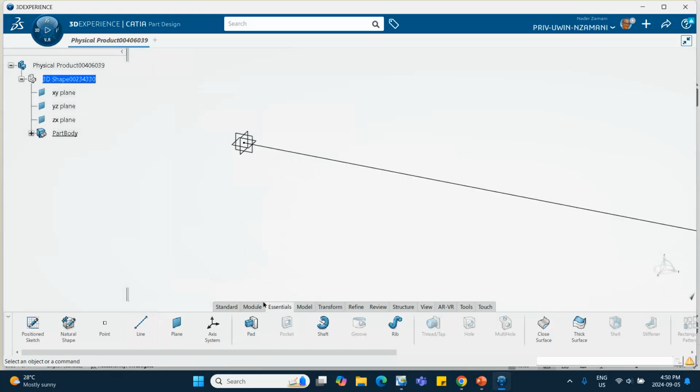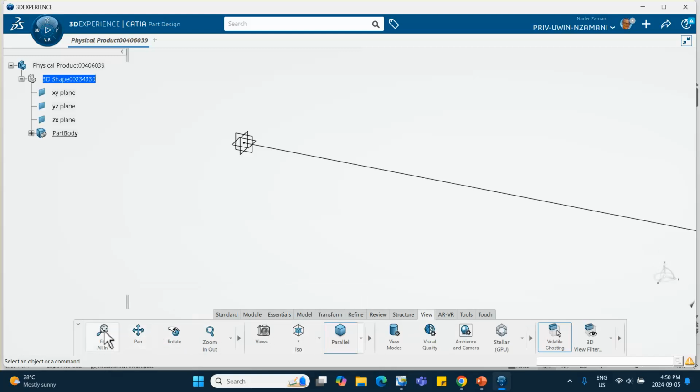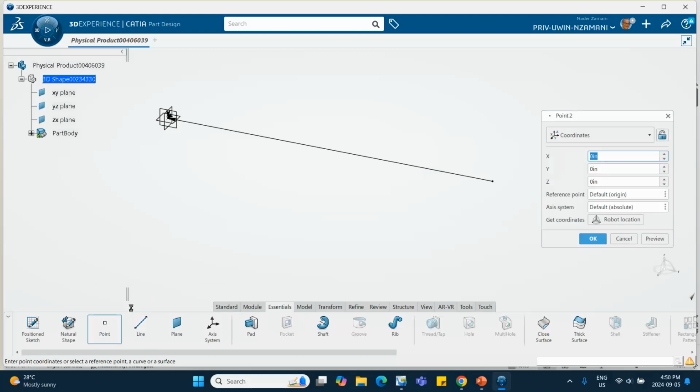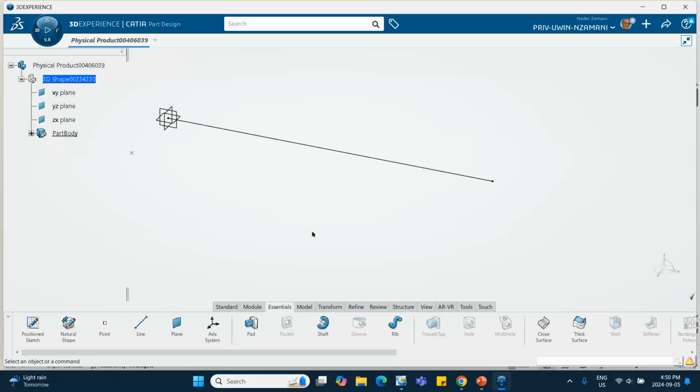All right, good. So let's fit this thing right here. This is my line that's going to be meshed with beam elements. Now, I also need an orientation point, so let me go ahead and create a point. Just for visual purposes, I'm going to create it so that it's maybe 5 inches away from where it is right now. This orientation point, remember, cannot be on the beam itself, on the line itself.